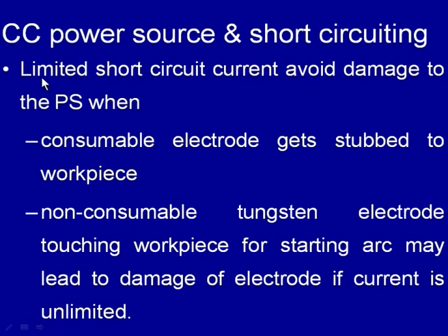In this case, a limited short circuit current is achieved in the case of constant current power sources, and this limited short circuit current helps to avoid any kind of damage to the power source. This is a very good feature related to the constant current type of power sources.